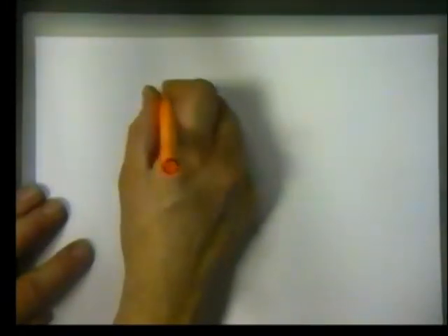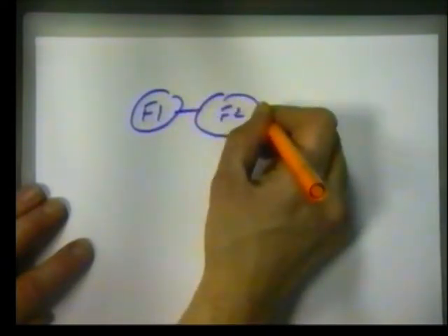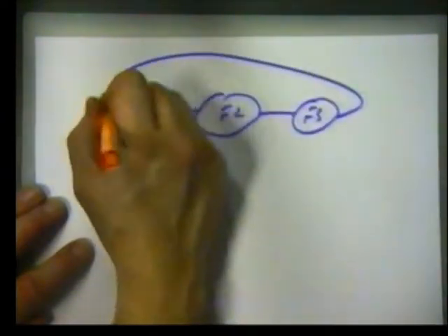The only way you can do it is by overlaying on top of the operating system specific requirements that put certain functions have high priorities and they must have fixed periods of time. And that sort of operating system gets extremely complex. Forget it. Go back to something simpler. Things that are simple are much easier to manage and maintain. What is the simplest sort of operating system? Well, if we've got 3 functions, why don't we just call function 1, then we call function 2, and then we call function 3, and go back to the beginning.